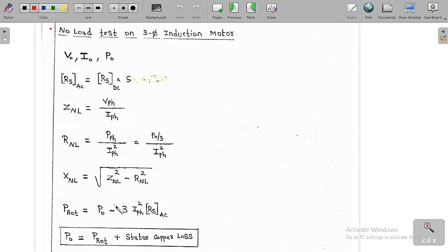And there is one more, called the mechanical power loss, or friction and windage losses. So now we have only 4 components: stator copper loss, stator core loss, rotor copper loss, and the mechanical losses. I have already told you a very important point, that the summation of the iron loss and the mechanical loss is called the rotational losses. Then we get something very simple: the input is equal to the losses, which is equal to rotational losses plus stator copper loss plus rotor copper loss.